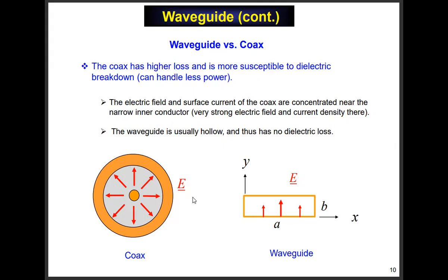Okay, that's a good question. Very good question. Thanks for asking that. Okay, first of all, let me say that distortion is something that's of interest for communication people, right? So when you're transmitting a signal from point A to point B, that's when you're worried about distortion. You're not really worried about that for power applications, right? So for example, nobody cares about signal distortion in your microwave oven. You're not carrying information. You're just transmitting a single frequency, 2.45 gigahertz signal from the magnetron into the oven, and you don't care what happens, as long as the power gets there, right? There's no signal, there's no modulation.